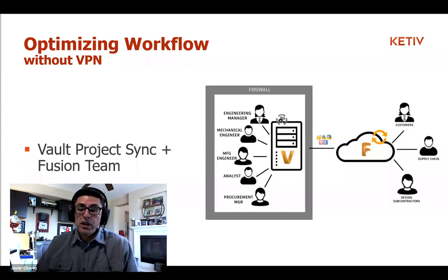So you're now copying Project A to the cloud, and from there you can share those, typically with customers and a supply chain and things like that. But who's to say we as remote users couldn't access that same cloud, make those edits, upload them, and have them sync back to the Vault? We can schedule this on a regular basis. We can create criteria for what files should be synced. It's another way of getting these files out of Vault onto our local machines where we can work on them effectively, and back to the cloud and to the Vault again.